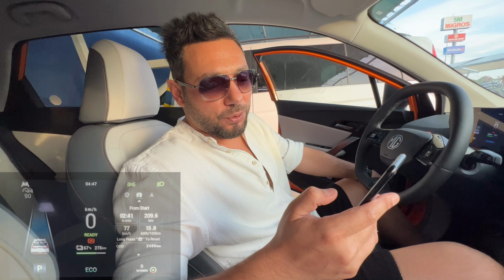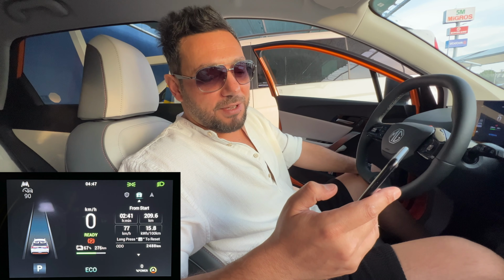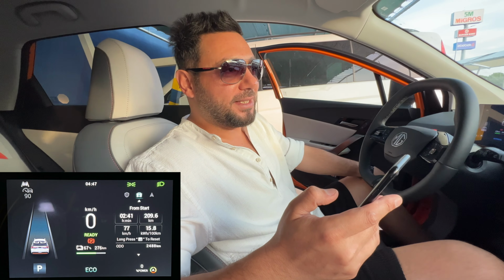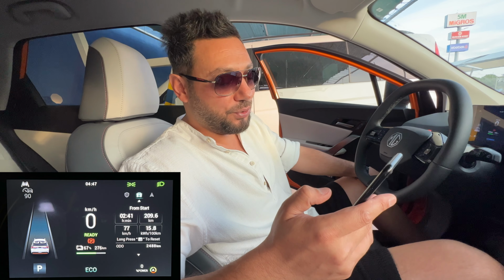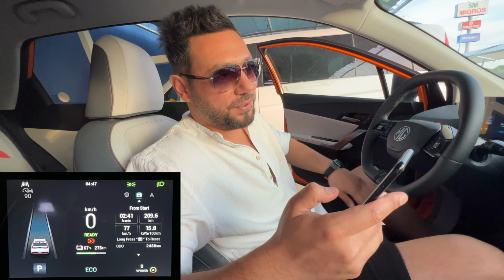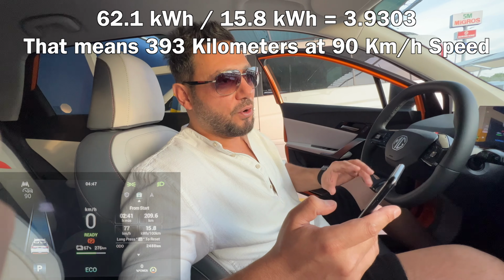The total distance we made on the Autobahn is 209.6 kilometers. Average speed 77 kilometers per hour, and average consumption is 15.8 kilowatt hours per 100 kilometers, which is more than my test at 100 kilometers per hour speed. That is because the weather was colder and the average temperature was 13 degrees Celsius. So when the weather is under 15 degrees Celsius, it affects the range of this car approximately 10 or 15%, which means with one full charge we can make approximately 380 kilometers at 90 kilometers per hour constant speed.